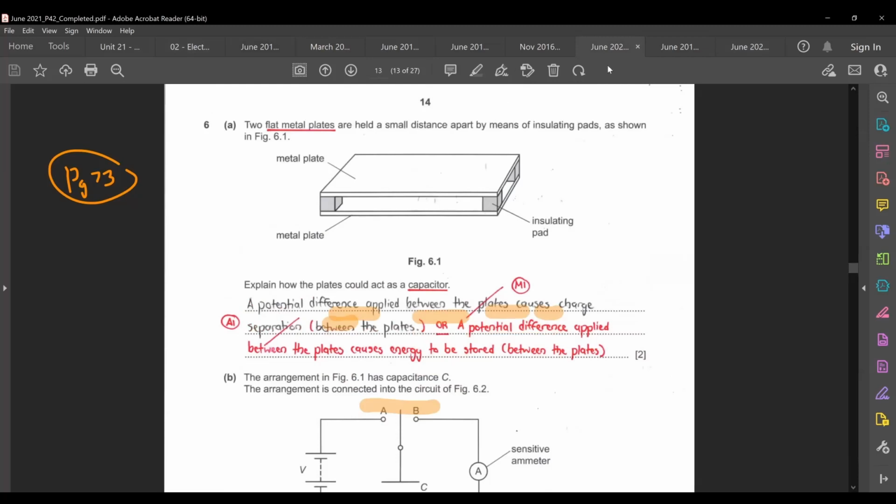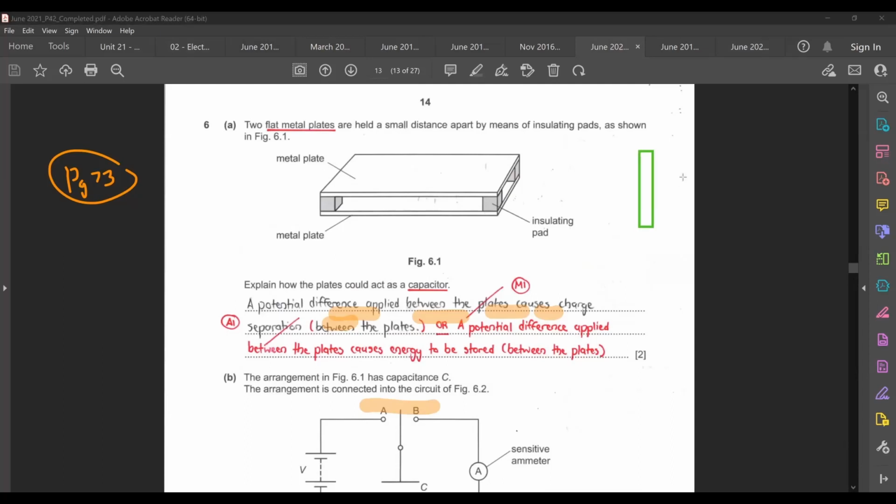So what you remember just now when I explained the capacitor was that you always need to have two parallel metal plates, which are separated by a layer of insulator, such that when you connect it across a voltage supply, say like this one, you will have a certain amount of charge caused by your electrons that try to move towards this plate and get deposited here, so that this plate becomes negative Q. And then likewise, you would have a similar charge, negative Q, being repelled away from the other plate, which causes this plate to become positive Q. Okay, that was how your capacitor became fully charged.